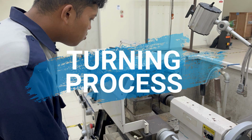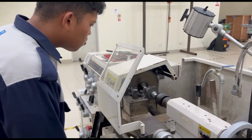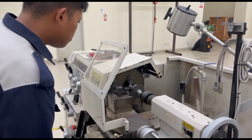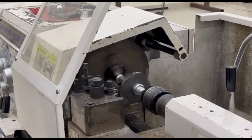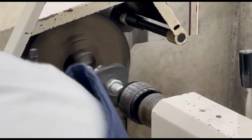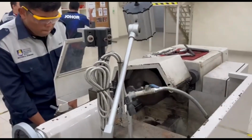For the turning process on the plate, firstly, put the plate on the cylinder and tighten it. Next, put the cylinder on the spindle and tighten it. Adjust the cylinder close to the dead center on the machine and it's ready to be cut. Cut the plate till the shape becomes a curl.